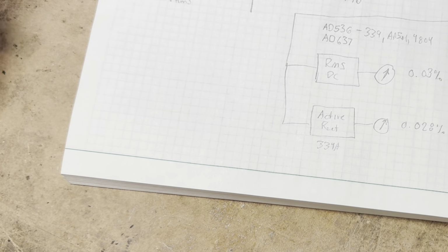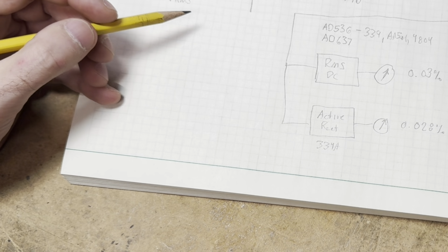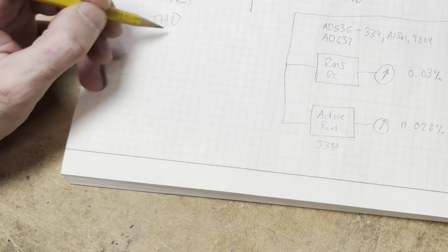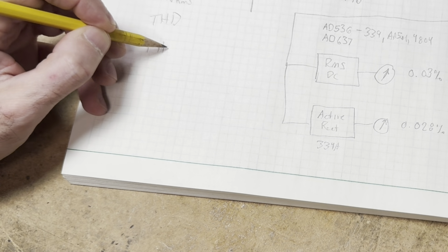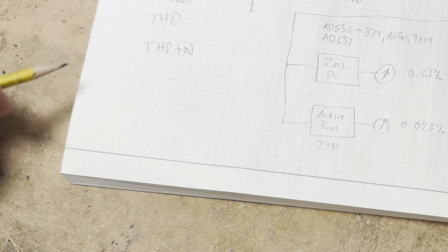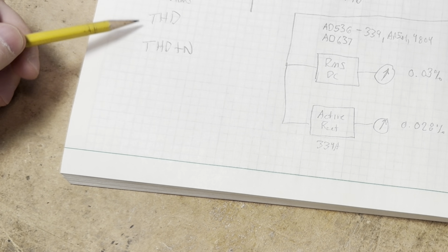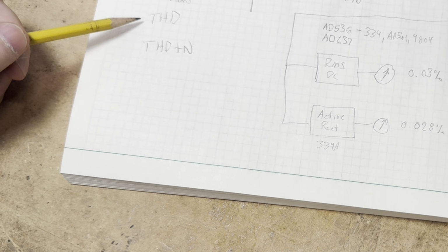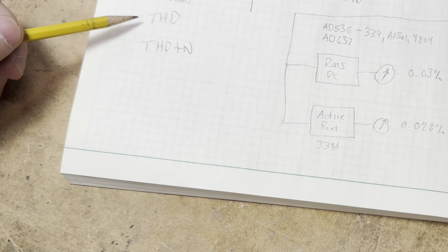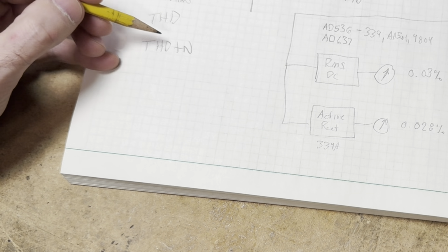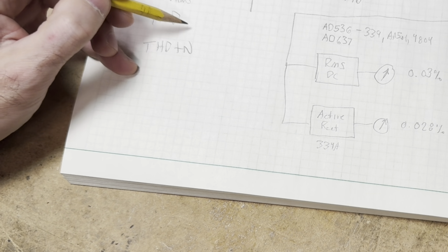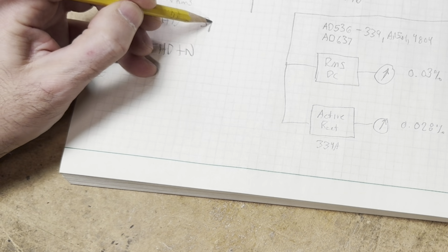Now, two more things to talk about here for distortion measurements. We talk about total harmonic distortion, and we talk about total harmonic distortion plus noise. So these are two different measurements, and sometimes I may use these interchangeably, but technically, they're not the same. They're different. Total harmonic distortion is when we look at the harmonic content of a signal. This will be something that we would do with a spectrum analyzer,